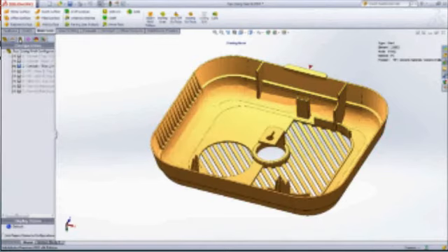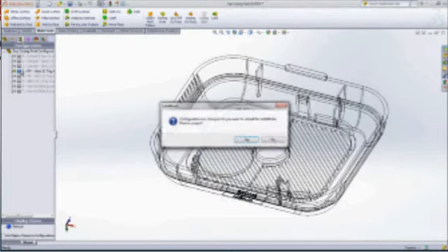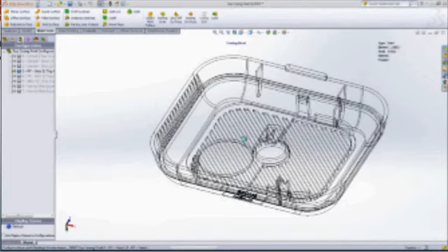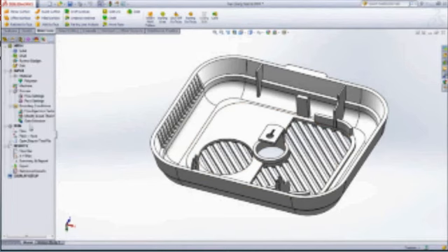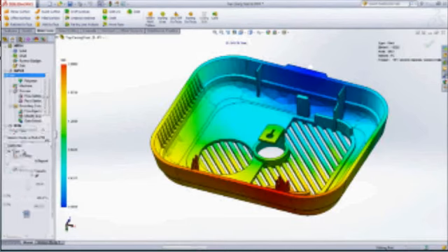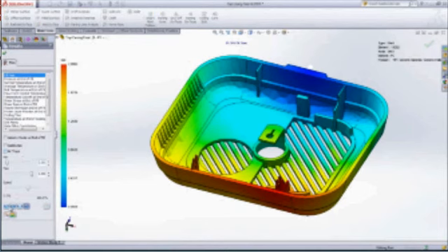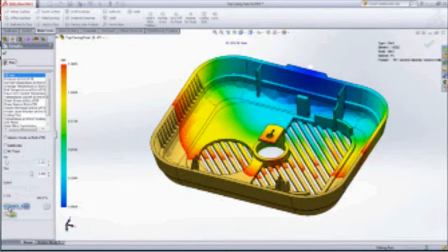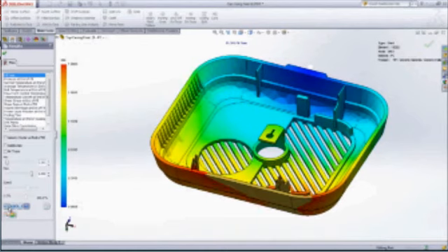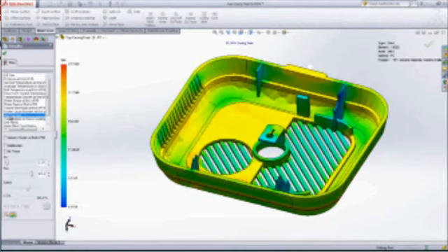This new configuration features a slightly higher wall thickness. You can see from just looking at the fill time plot that we can now fill 100% of this cavity without reaching the maximum injection pressure of a molding machine. The cooling time, which is the time it takes for the part to cool to a temperature at which it is safe to eject the part, is reduced significantly by more than 50%.